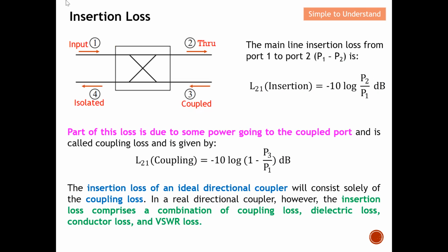Next, what is an insertion loss? Insertion loss means what will be the loss, let's say from port 1 to port 2. There will be some form of loss from port 1 to port 2. So the main line of this insertion loss from port 1 to port 2 is simply governed by this equation here. So this will be known as the insertion loss, how much power is lost. So in short, as I mentioned earlier on, this will be the source, and this will be our so-called final destination where we want to send over the power.